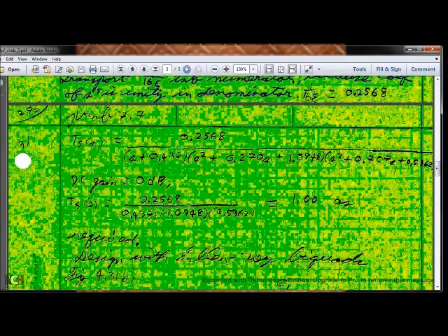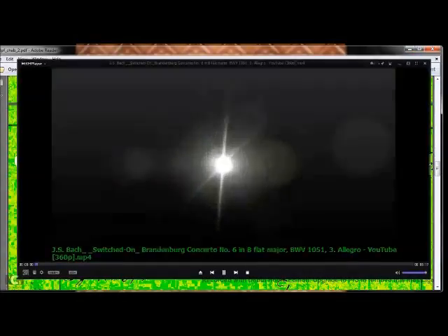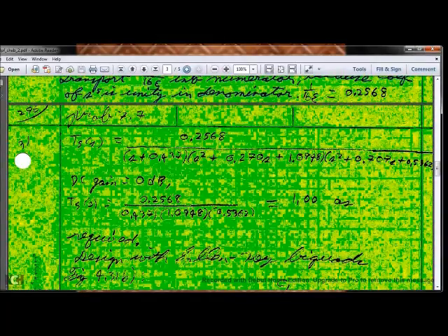Here we have a numerical value for our transfer function, T sub 5 of s. 5 is the order of the filter. We have 0.2568, capital K, in the numerator. Here we have the first order section. We have a second order section here. Sorry about that, we get our image back on here. And we have a second order section.